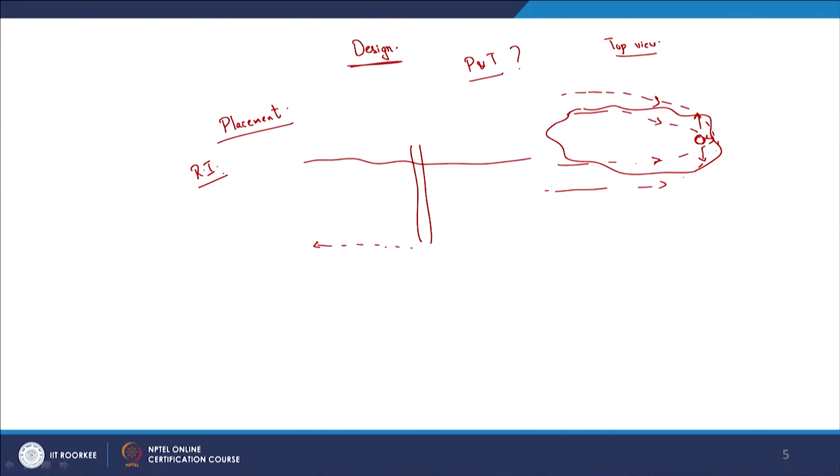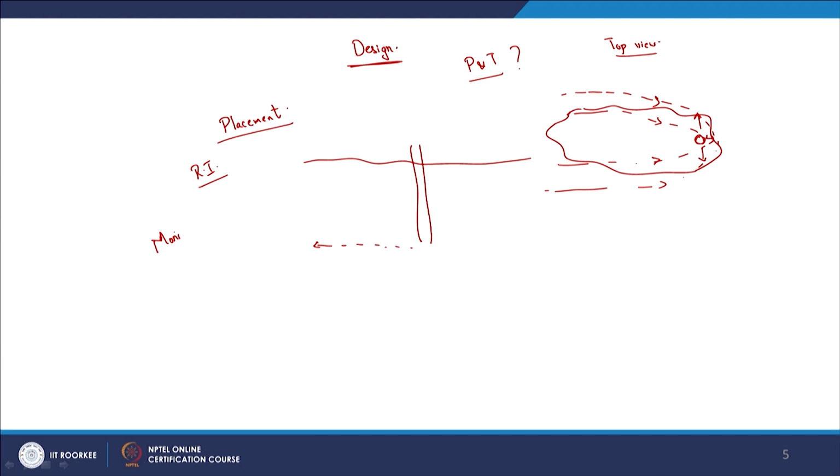If I am pumping air out from here, or introducing a vacuum source here, as I move away from this source the effect is obviously going to be relatively less. Based upon which source or literature you look at, there are different ways to calculate what I may call the radius of influence. You will have to calculate that radius of influence, and then look at relevant placement and so on. Obviously, one aspect is that you also need monitoring wells, other than just your extraction wells.